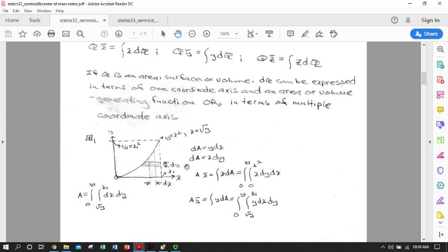And you can express invertible functions in terms of x or y. You know, the independent or dependent variable, you can switch them in a lot of cases. And so that gives us some options on how to execute this, because for a continuous function that doesn't have a defined shape, we're probably going to have to do an integral just to get q. Then we're definitely going to have to use integration to do x dq, y dq, or z dq. So sooner or later we're going to be looking at how do we integrate functions over defined limits to actually evaluate our centroids. We're going to have to get our total area or volume or length, and then we're going to have to evaluate the integral of the distance to each bit of area, volume, or length.